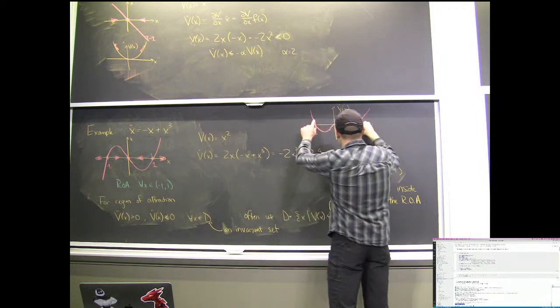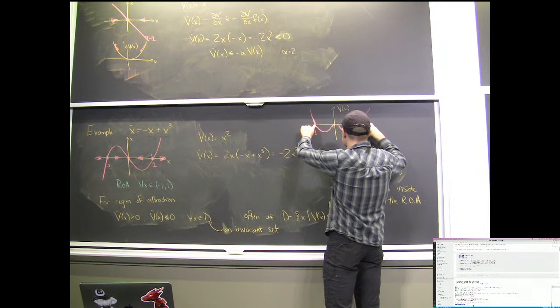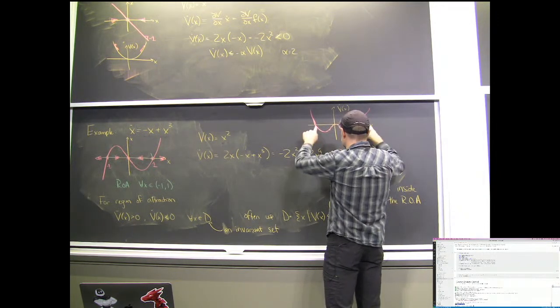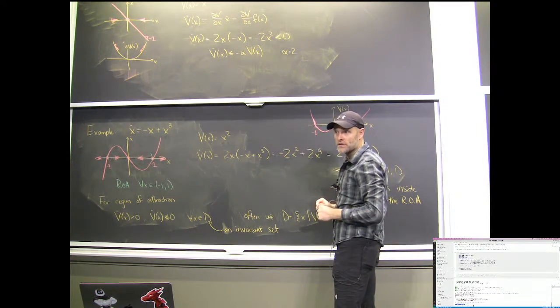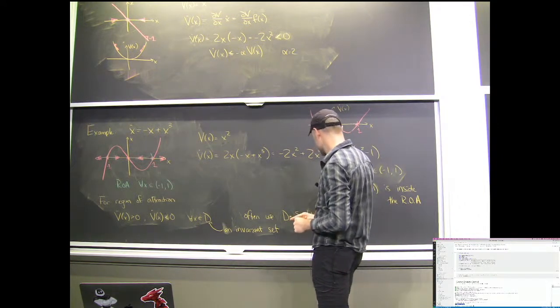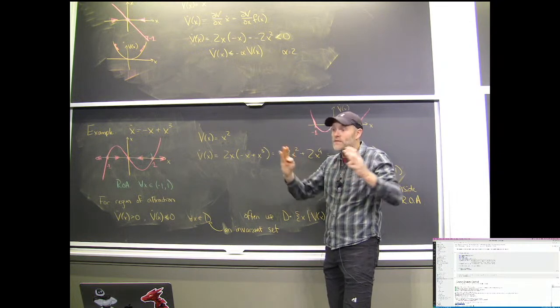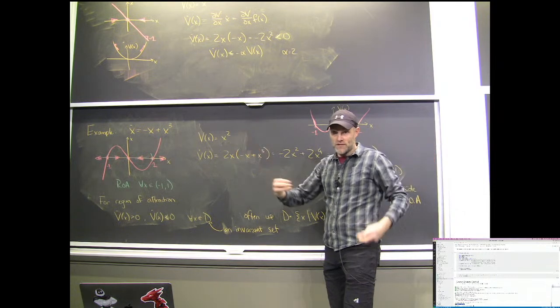I knew that once I was inside -1 and 1, I won't leave, and I know that V dot is less than 0. Together, those certify that this region is inside the region of attraction. I say inside the region of attraction because having a Lyapunov function only says that; it doesn't say you found the biggest invariant set. The region of attraction could be even bigger.